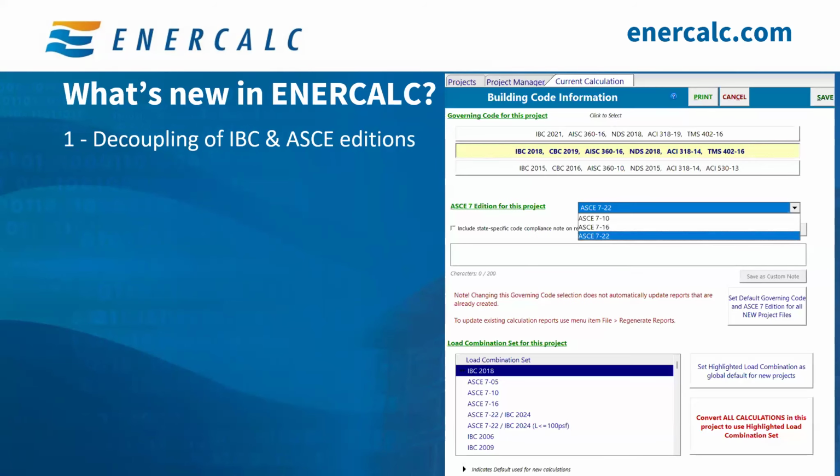Some jurisdictions have started mixing and matching design standards. So, for example, a jurisdiction might be using IBC 2015, but it wants you to use ASCE 7-16. So these are not matching, as you know, IBC 2015 references ASCE 7-10. So the standards here are not matching the referenced code. Previously we used to have everything lumped together, so the IBC edition is lumped together with all of the other standards based on whatever edition they reference.